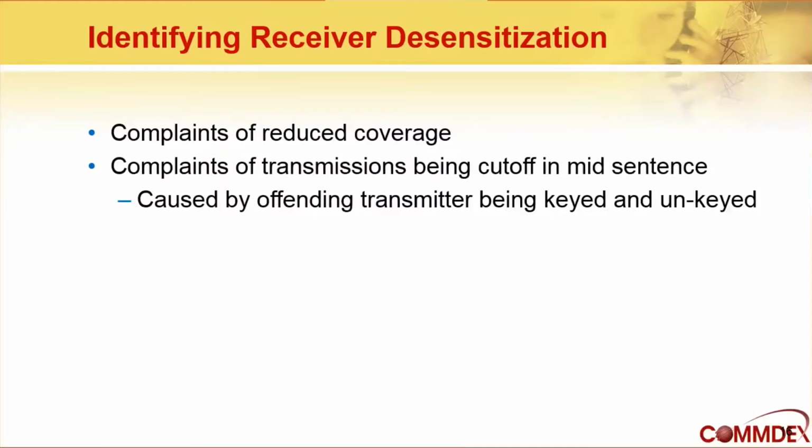If interference comes from a broadcast transmitter, you can listen to it, it's continuous, and you can ID who it is. And that's great if it's a high-powered broadcast transmitter, but oftentimes it's going to be some intermittent transmitter that you have to be lucky enough to hear when it happens. So you may have to place some equipment on site and walk away and let the equipment listen for it to happen. It may only happen once or twice in a 24-hour period, but just enough that the user gets annoyed by it. So it takes patience to track down interference, and we're all patient people.